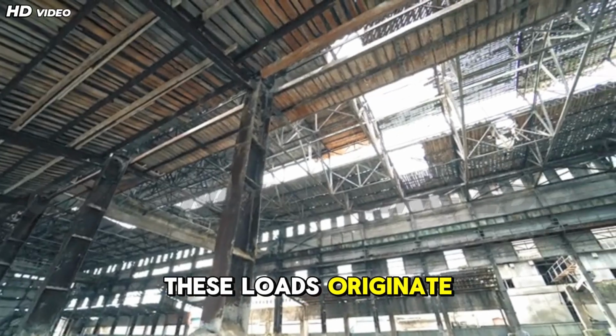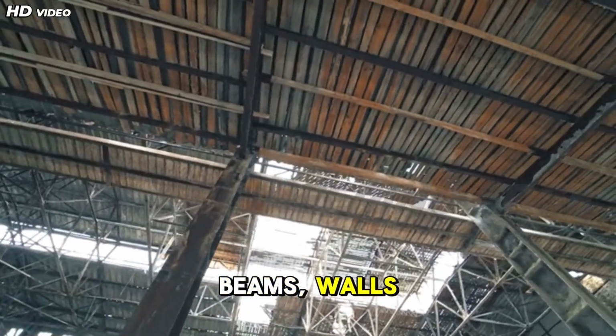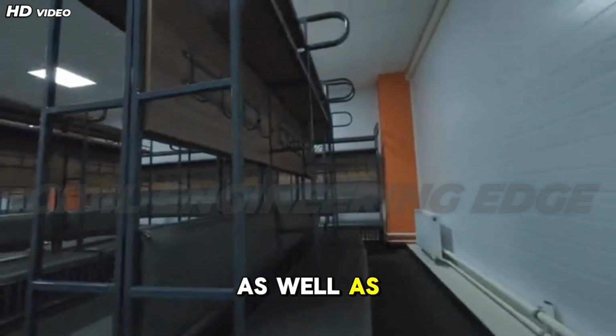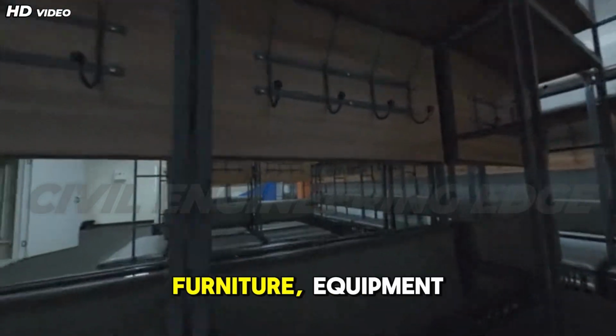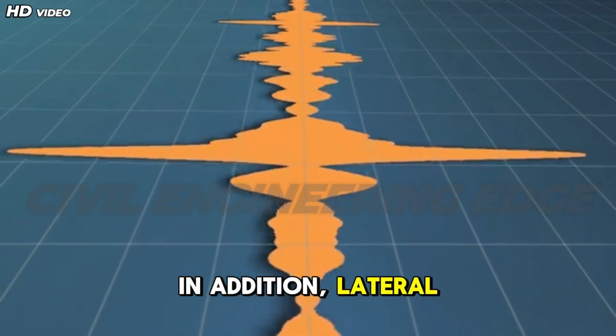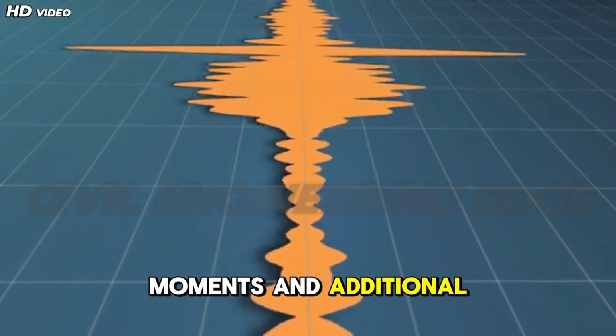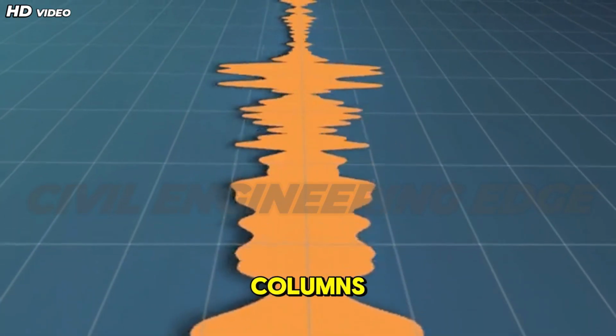These loads originate from dead loads such as self-weight of slabs, beams, walls, and finish, as well as live loads due to occupants, furniture, equipment, and vehicles. In addition, lateral loads from wind and earthquakes induce bending moments and additional axial forces in columns.